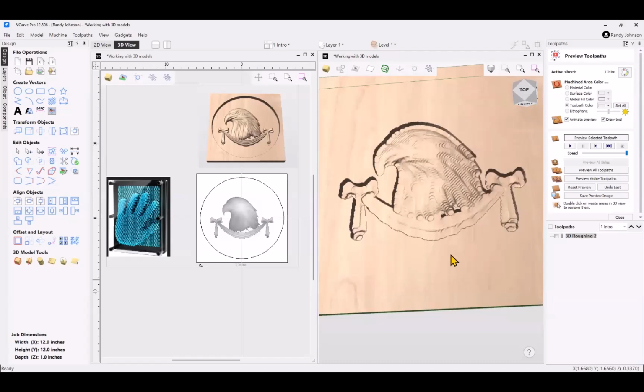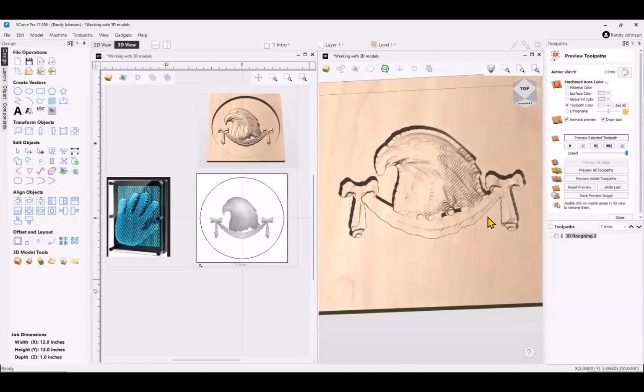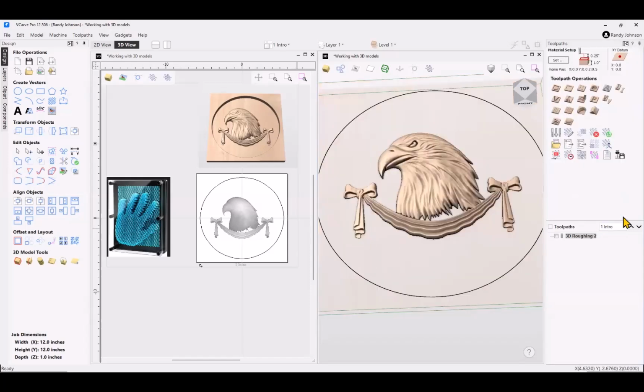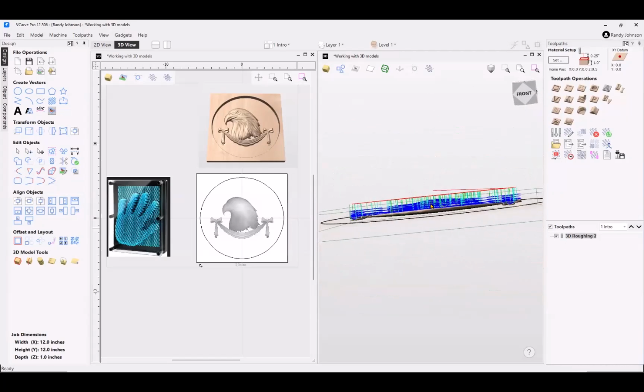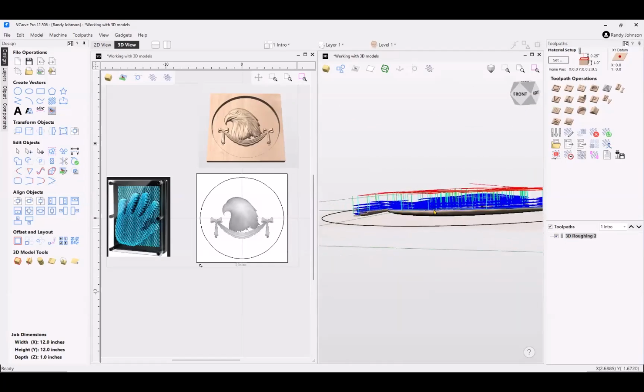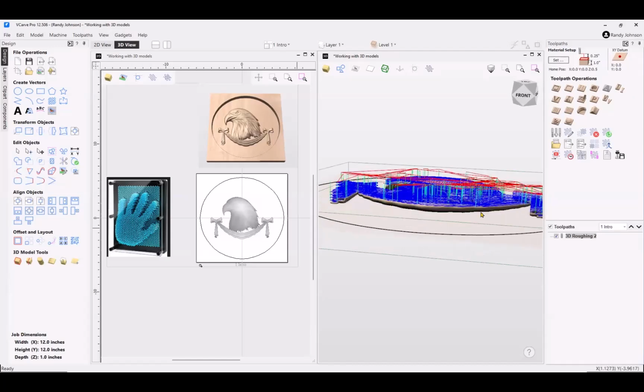Some of that may chip off during machining, and it may or may not be an issue, but you're going to see when we get to 3D finishing, it becomes a little bit more of a problem. And that's because that's that gap inside that opening there. So 3D finishing, the 3D roughing sets up, if we look at the side here, you can see it setting up with multiple pass steps going down. So whatever your pass step, 1/8 of an inch, 1/10 of an inch, 0.05, whatever it is, that's what it's going to cut in those pass steps.